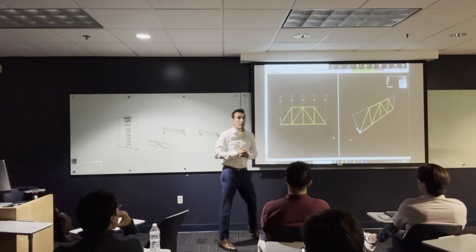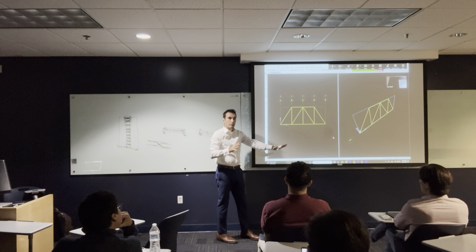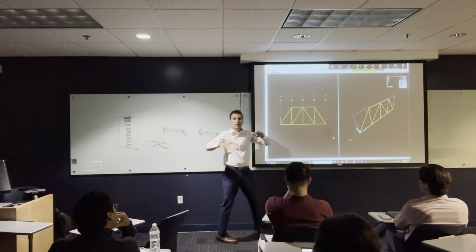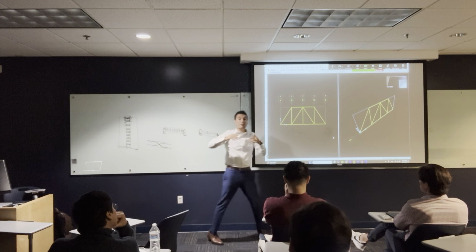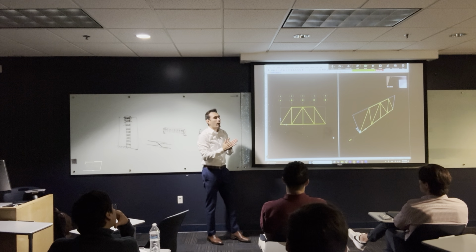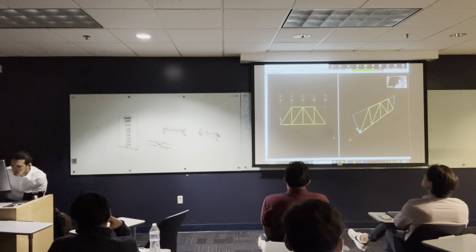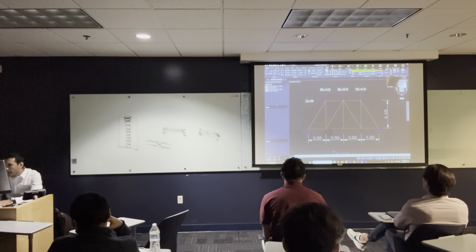Apply supports. This thing by itself is unstable. Once you put the load and run the analysis, it's gonna have a deformation of a millimeter because the thing is gonna flip away, like it's gonna be unstable. Okay, so I wanna put the support. Basically, you select the point that you wanna put support at. Let me check here. I have a roller on the left, hinge on the right.